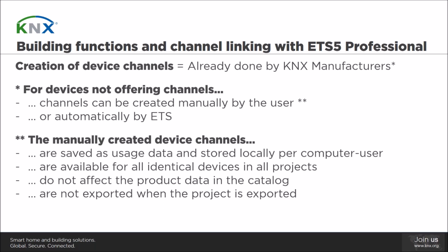Furthermore, what is also important for you to know is that if a device implements already channels, meaning that the manufacturer has already defined channels for the group objects, then it's not possible for the ETS user to add them. Simply spoken, because the group objects within the channels may contain metadata in order to allow smart linking, something that we will see a few slides later, and editing those channels would invalidate those metadata, and that's something that we do not want to do.